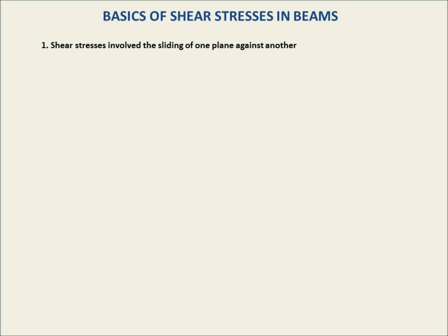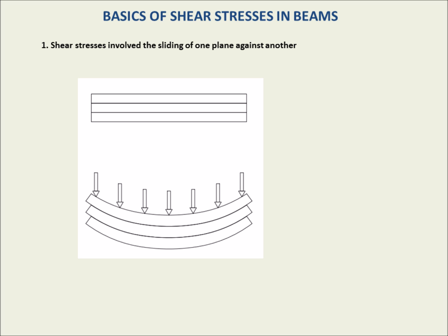Now, how do shearing stresses get introduced to a beam that is primarily in bending, a member with length that's transversely loaded and that bends? How do the shear stresses get involved? Well, let's look at a diagram here, and the top shows a beam which is made up of 3 layers. Maybe it's 3 pieces of plywood. Maybe it's 3 rulers just stacked up against each other. And the top part is unloaded. The bottom part is loaded with loads transverse to the length of the beam, shown with arrows pointing down. And then we have a deformation, our usual smiley face deformation.